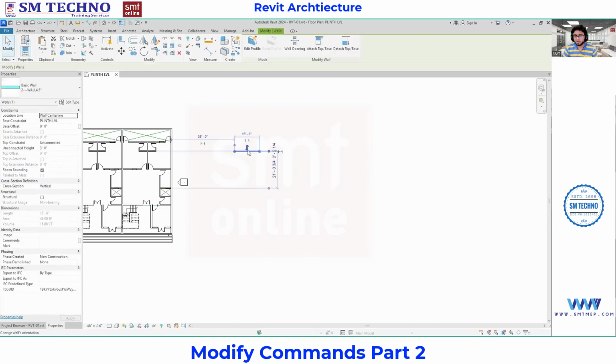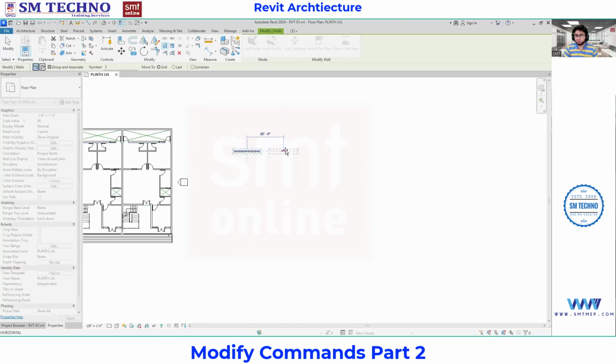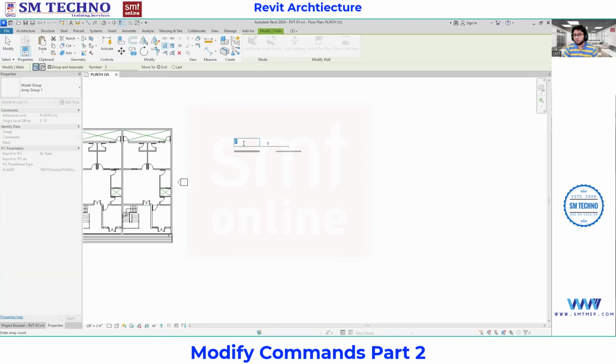I'll just repeat again. Select the object, I'll go with the array. In the array, we have linear as well as radial. We have got group. Always keep group enabled, or else the objects will shuffle. How many items you want, you can specify from here, or else you can go with the work plane also. Move To, second means from the center of this object to the center of the next object, I am going to keep a distance of 25 feet. When you select this, it will ask you how many objects you need. Like here I have given 2, here also you have given 2.